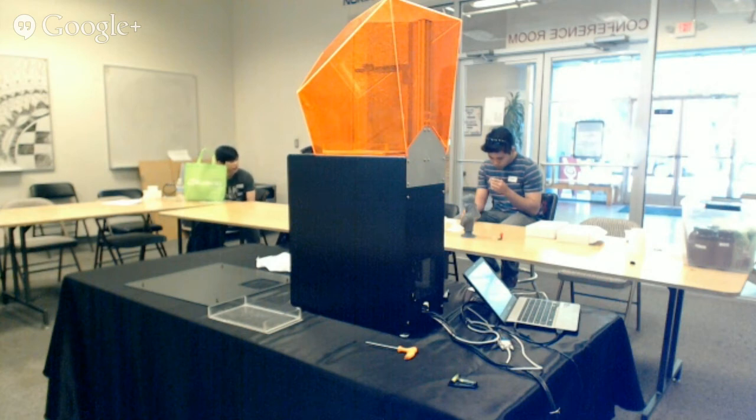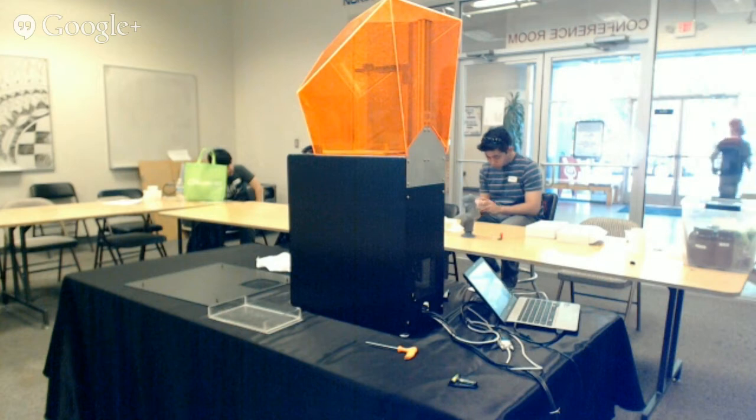But baking it as in UV baking or temperature baking? I've only done UV, but people have said that depending on the polymer composition, temperature baking also makes a difference. Because in a highly pigmented piece like this, the UV that I shine on the outside is never making it to the center of the part. And so the center of the part is always going to be different.